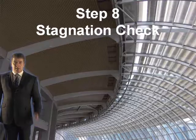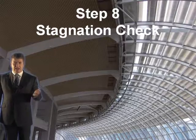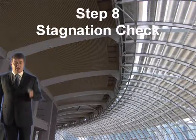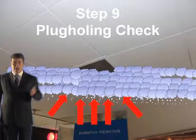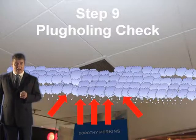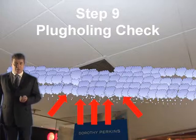Step 8 is your stagnation check. Again, this only applies to natural ventilation. We're using mechanical extraction, so you can ignore this step. The next step is the plug holing check. This applies to both natural and mechanical ventilation. You've got to carry out a plug holing check.